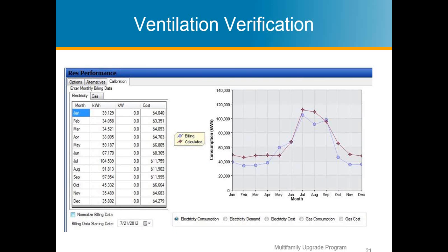Like I said, and I'll say it again, you want to be able to quantify that energy use. It might not be a super inefficient bathroom exhaust fan that's bringing the building's billing up higher than the calculated usage. It might be some other things you find, and you're able to then do hand calcs on the side to interpolate that into maybe a watts per CFM. You need to be able to explain how you got to that number. You can't just plug in a number and hope that the lines match up.